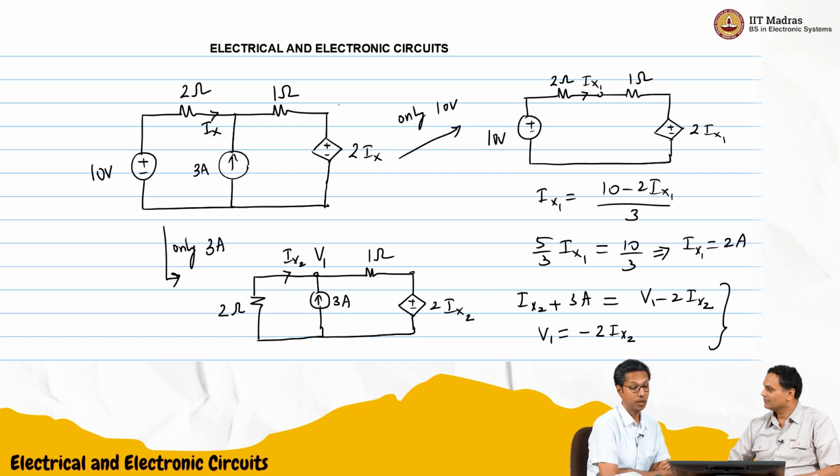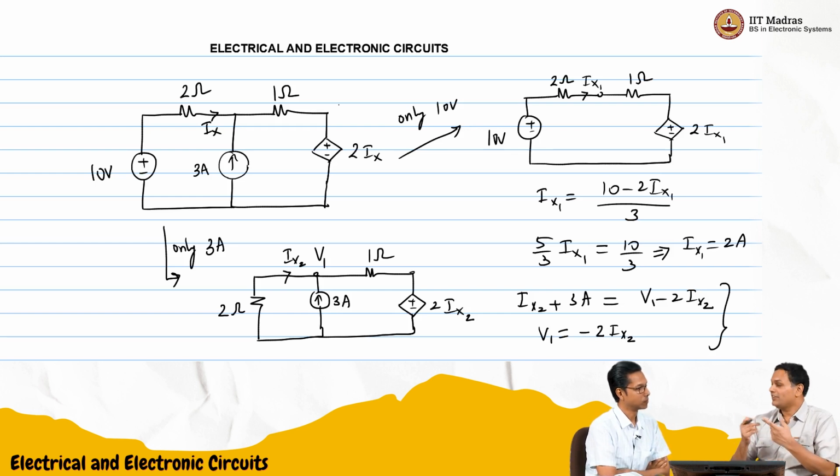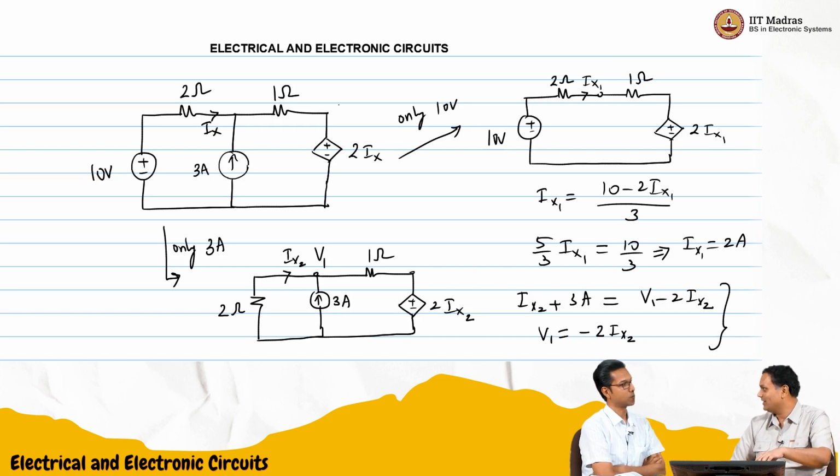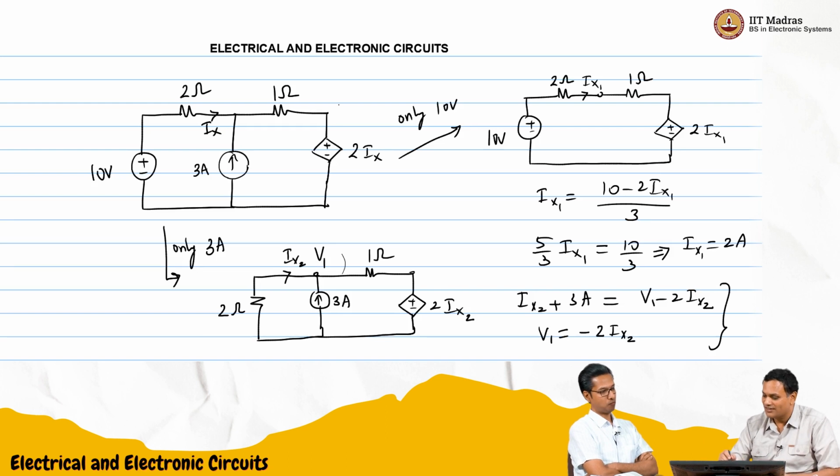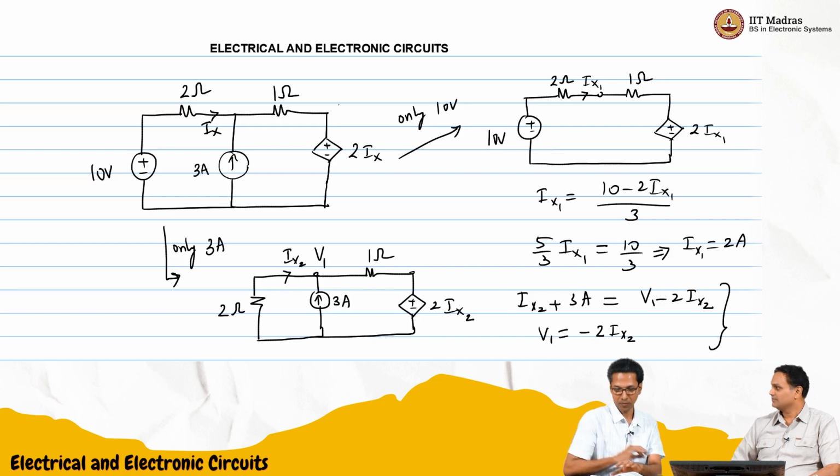Now I am curious, what will happen if I use Thevenin and Norton? Two things we have to keep in mind. We have seen you can't remove the controlling variable or change it completely. Like you can't do source transformation for this. Of course VTH will be okay to find out, but RTH may be tricky. We'll take one simple example.